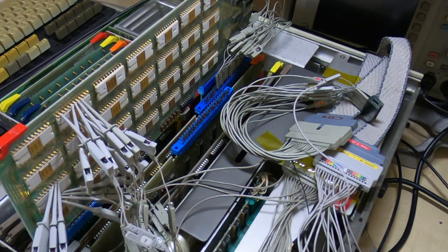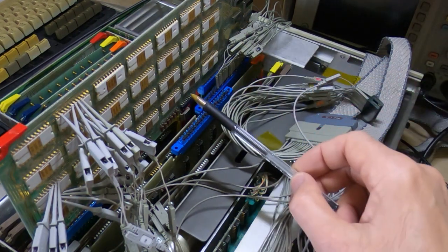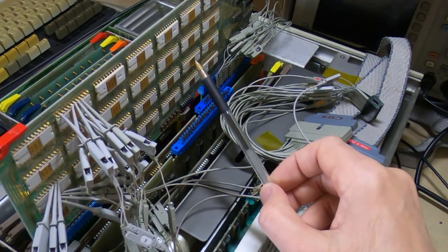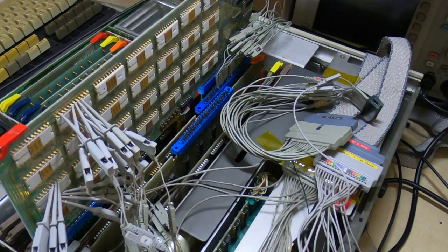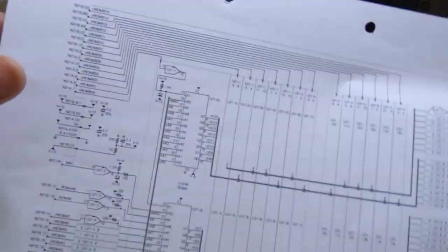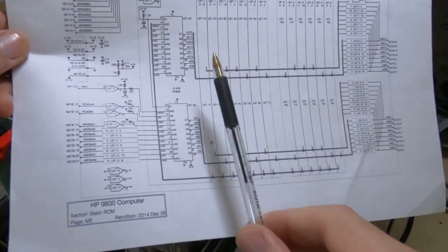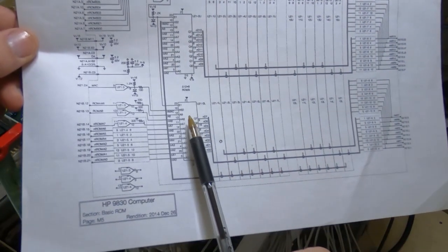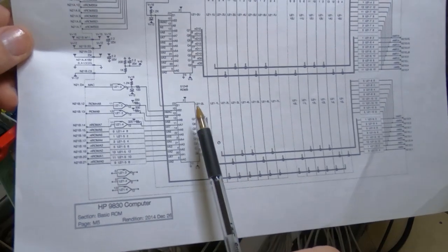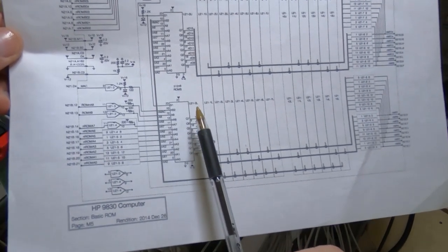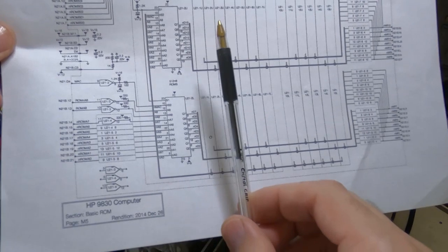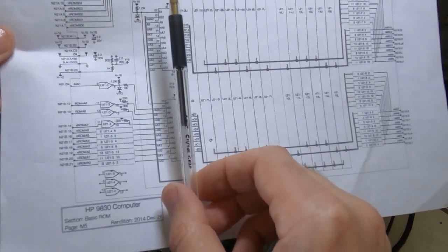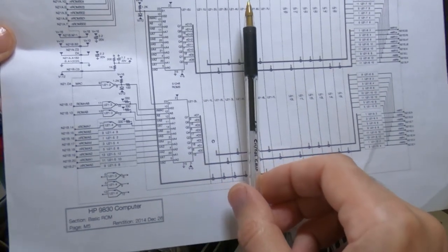Now the main system code resides in this board. It's a series of mask ROMs, so it's relatively simple in the way it's configured, although there are some oddities in it. Firstly, in the decoding of one of the address lines, there are two pins for one address line, one high, one low. I'm not quite sure why they've done that. But essentially the way it's configured is in blocks of 2 ROMs per address space.